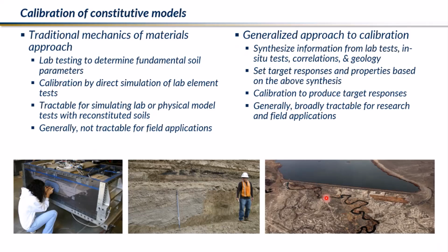When you go into the generalized approach to calibration, which is what we have been trying to promote from the use of this model, not so much in their development, it goes to the fact that you're synthesizing first all of the information you have at your site, from your lab test, the geological information, past observations, and so on and so forth. You set target responses after having reconciled any differences, and then you calibrate a model that will honor those responses. The constitutive model doesn't have to be PM4, it could be any model; it will not reconcile issues that you have from the field characterization, and it's important to separate that.